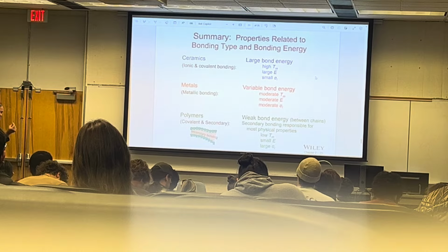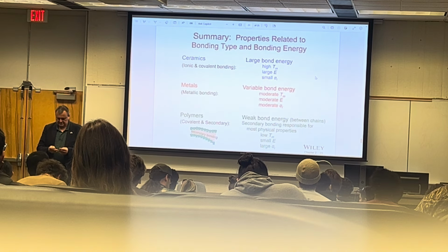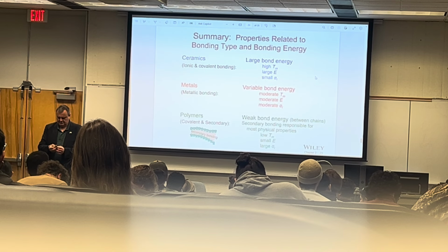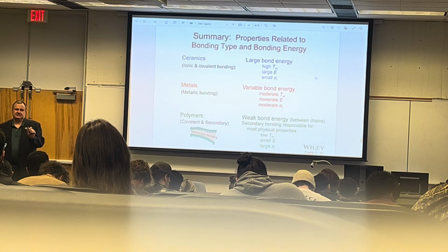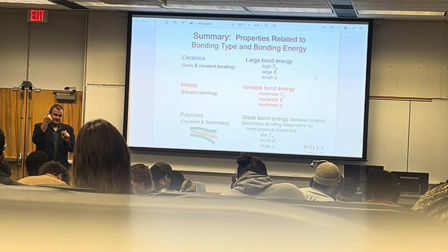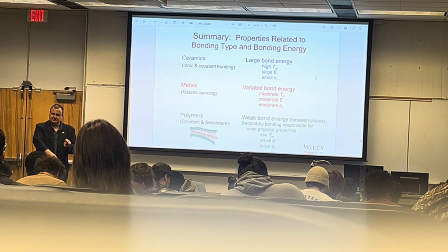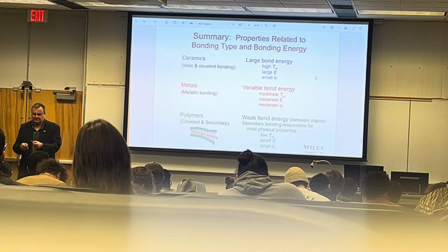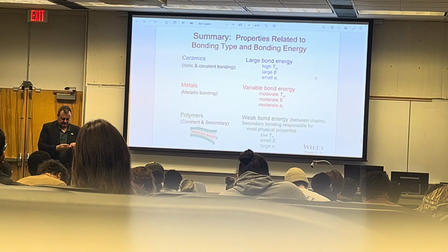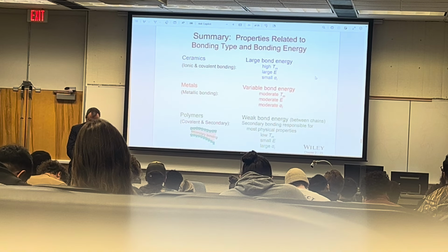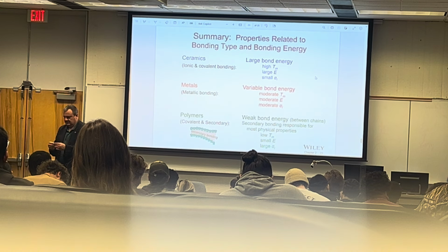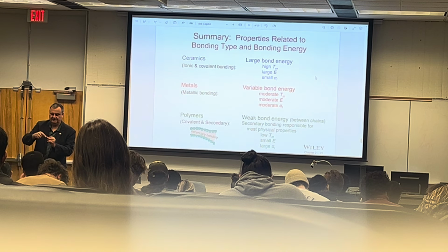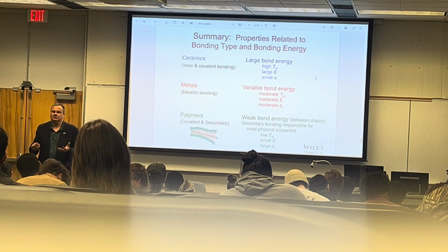What's the reason? Why did this fail? Yes? They're both bent. And the reason they're bent is because the incandescent bulb emits light all the way around. I don't know if there's a reflector, but these are bent so that the light goes towards the license plate, not the other way around. How many components does this have? You see that there are two chips here on one side. There's another chip here on the other side. See that? They're actually electronic components. And then there are LEDs on this side, and then on this side, and on this circular side, so that the light simulates a regular bulb.